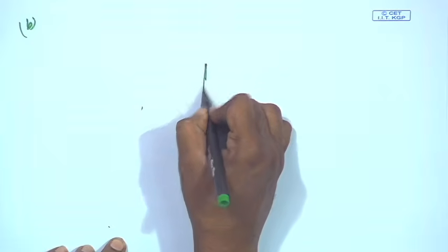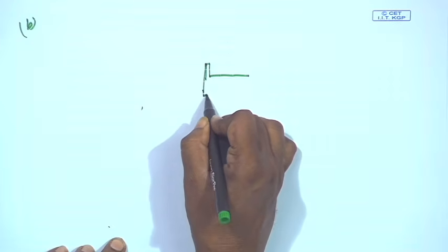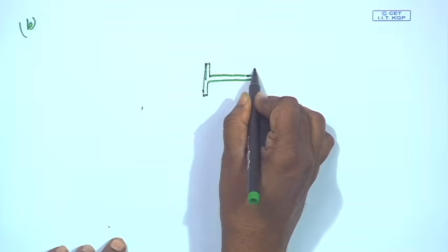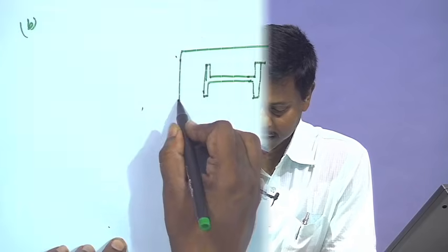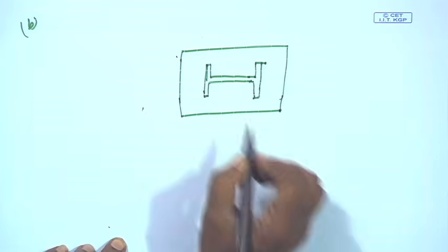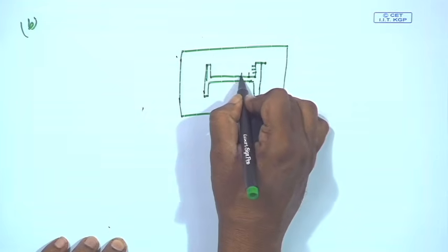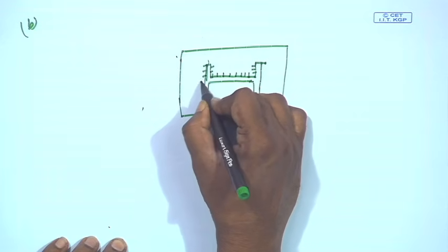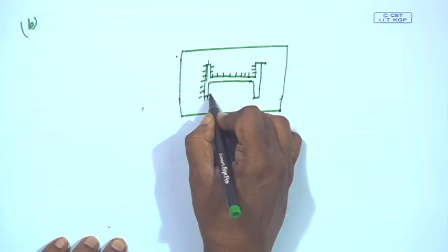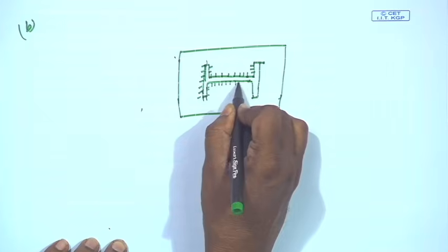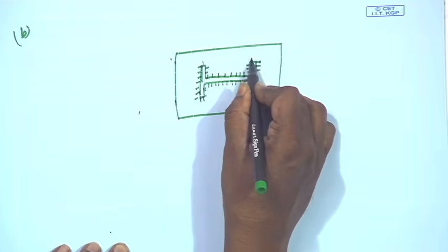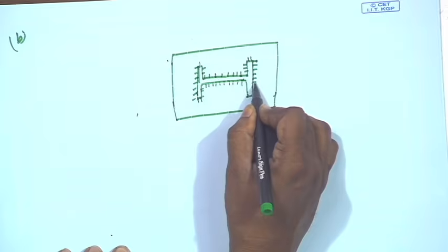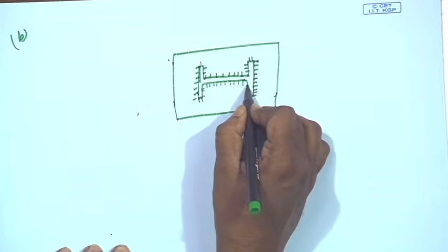If we see the weld connection, the base plate is connected with the column, so there will be a weld connection throughout its periphery. Now, I have to find out the total length available for welding and the required length to withstand that load.